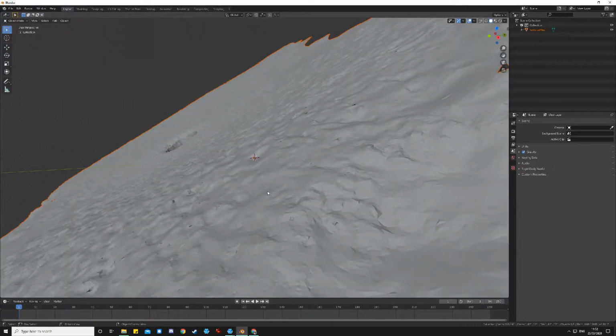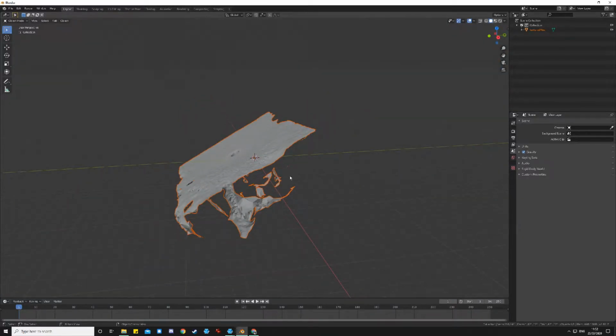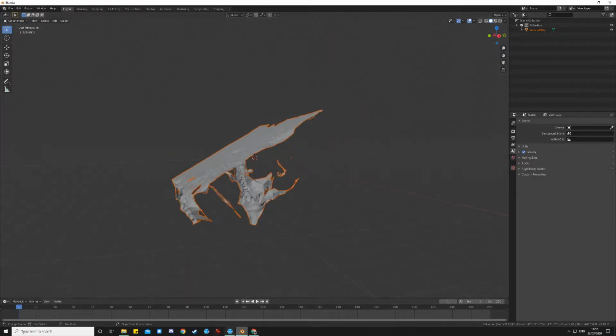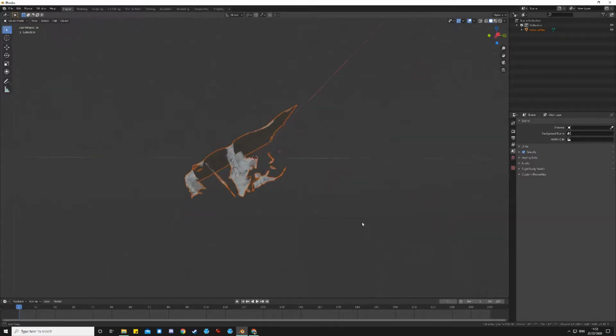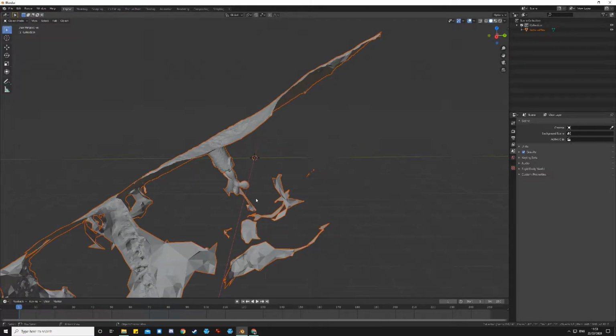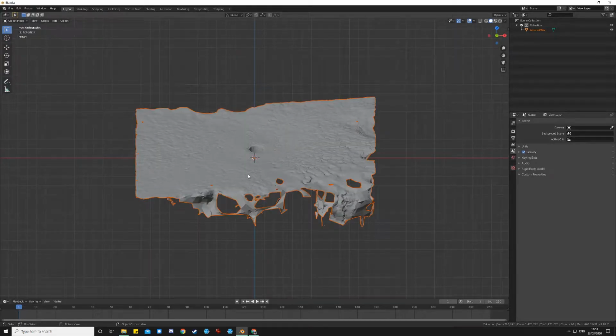And there we are. And you'll see, oh, that's a bit of a weird shape. Well, it's because if we zoom out using the mouse wheel, you'll see that it is the same object, it's just upside down. This is because Meshroom doesn't really know which way is up. It's able to extrapolate the difference between the different parts of the picture, but it doesn't actually know that the ground is the ground and the sky is the sky. So you have to right it the correct way around first. So what I would do first of all is press number 1, which gives me an orthographic side-on view of where the bottom is.